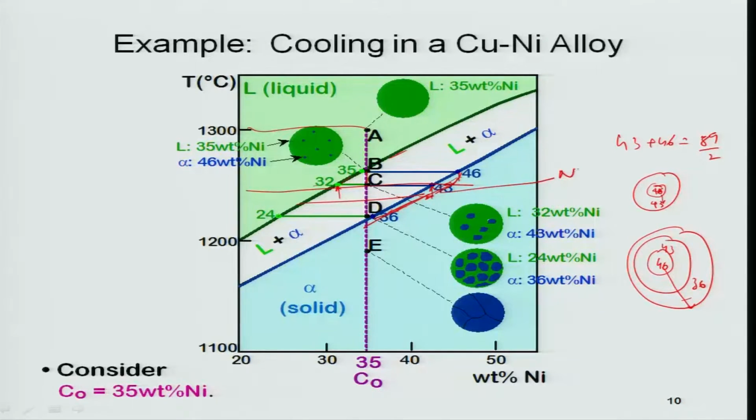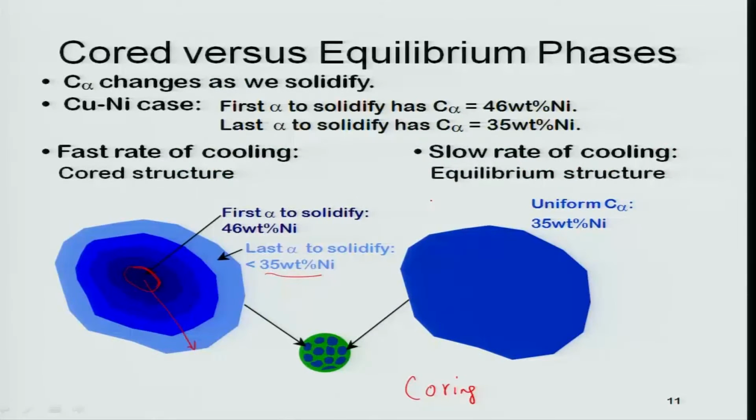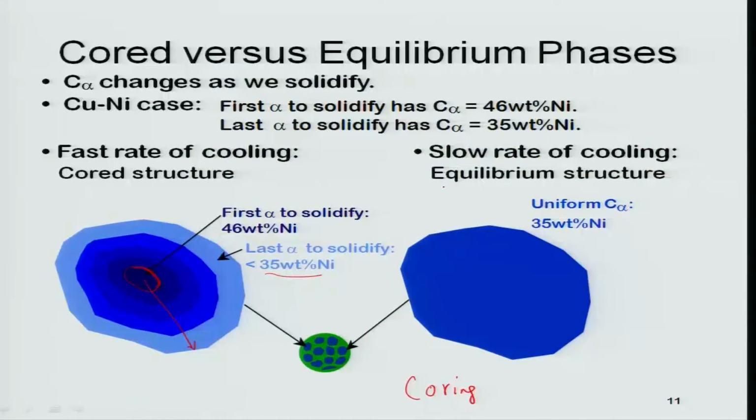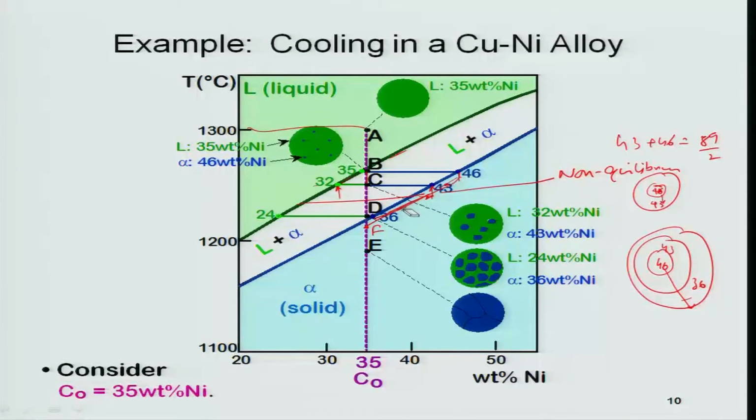So this is known as the non-equilibrium curve. Because of this non-equilibrium curve extension, solidification will be over at a point, suppose F, which is lower than point D, or lower than the liquidus temperature. So under non-equilibrium conditions, solidification will never finish at the solidus temperature, it will get over at a temperature given by point F. I hope I am clear a little bit. So let me just again draw this and show you, or later again tell you how it is possible. Just a little bit of erasing will help you.